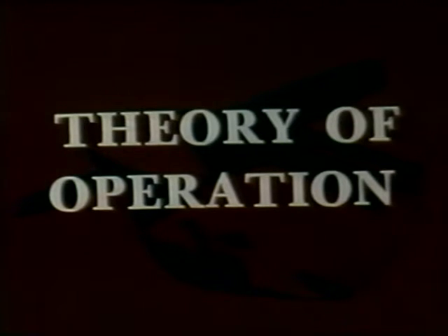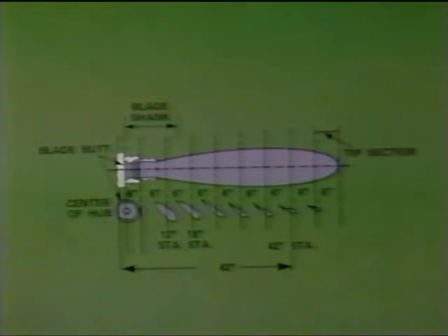Before discussing ways of varying the amount of lift generated by a propeller blade, it is necessary to understand some of the design characteristics. If the blade angle of a propeller were measured at each station along the blade, you would find that the blade angle near the shank would be the highest, with a decrease in angle toward the tip. This is known as pitch distribution and is necessary because each section is moving at a different velocity, with the slowest speeds near the hub.